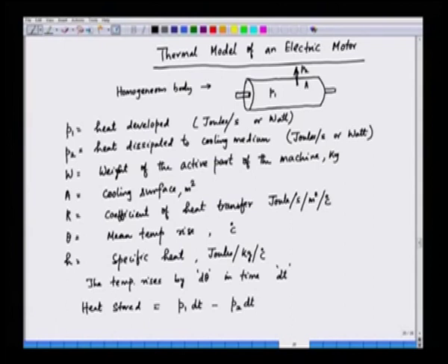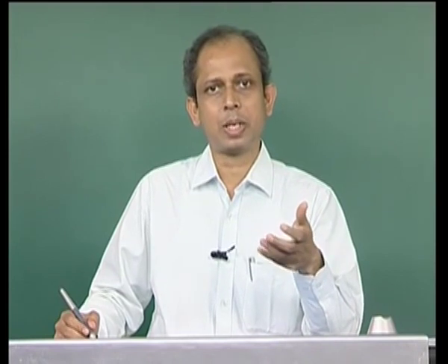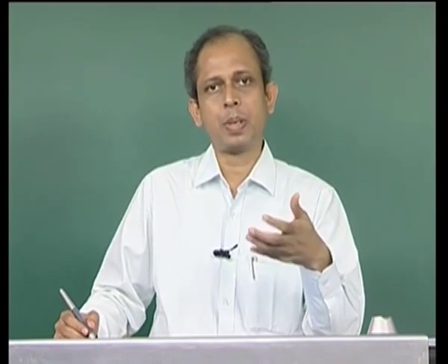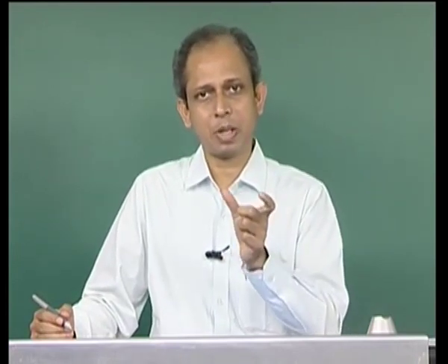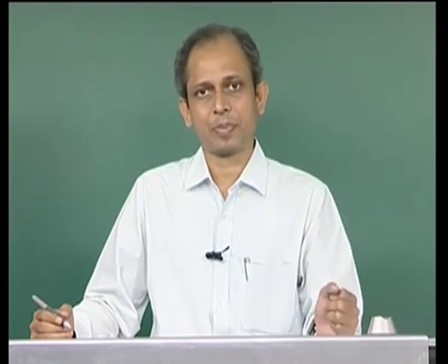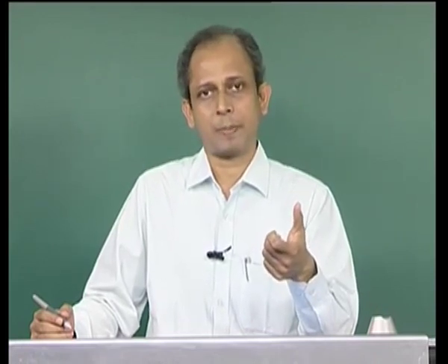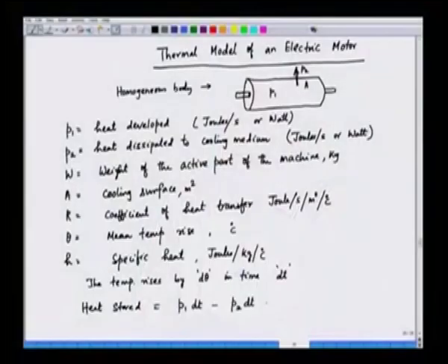This P1 is the heat generated inside the motor, it is basically loss of the motor in watt, and P2 is the heat that is dissipated to the cooling medium, and heat stored inside the motor is P1 dt minus P2 dt in an interval of dt time, and that heat is responsible for raising the temperature of the motor. So, we have the weight W, the specific heat H, and change in temperature d theta.